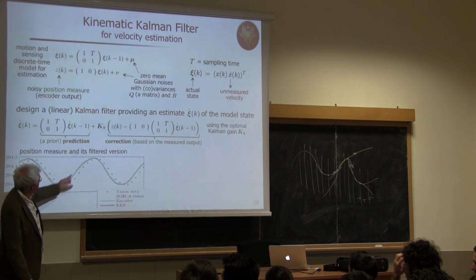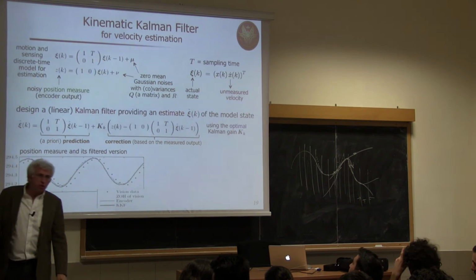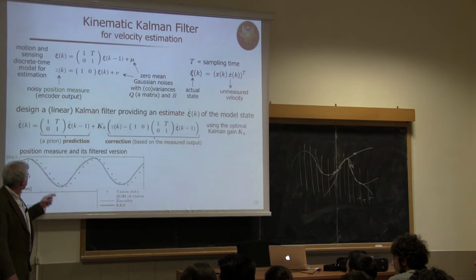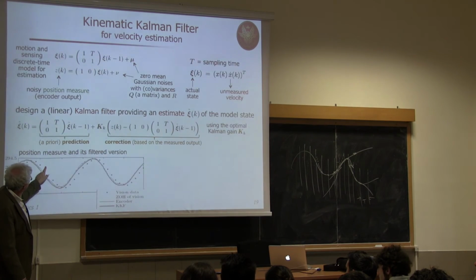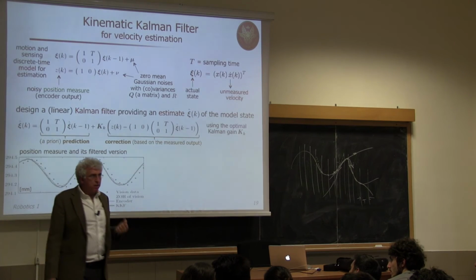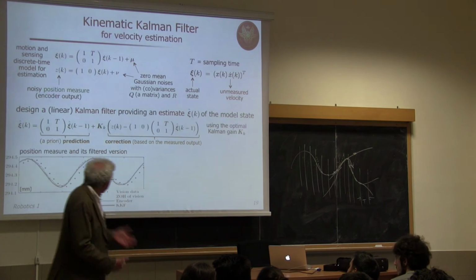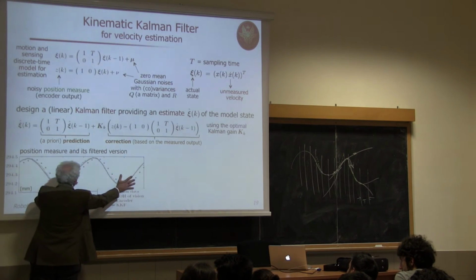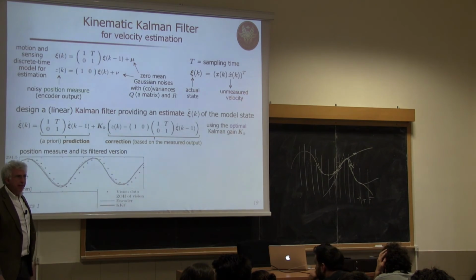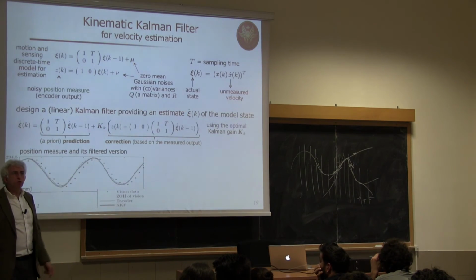And you can see that it's much smoother. And these dots are acquired by vision, by an external sensing, and they are held for one sampling time. So you don't see this, but they are held like this. And they are slightly in delay. Why? Because the vision system needs time to acquire this information. Okay? So there's a natural shift, but if you could move, let's say, one step ahead the vision data, you would see that they fit well with the estimated position that has removed the noise.